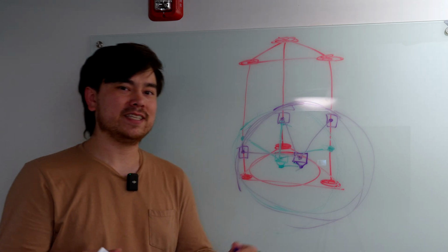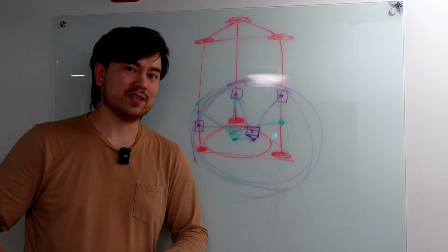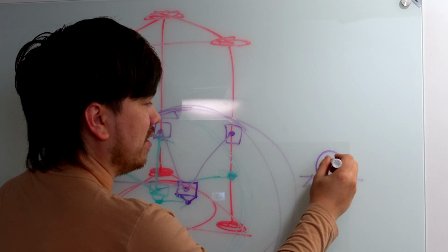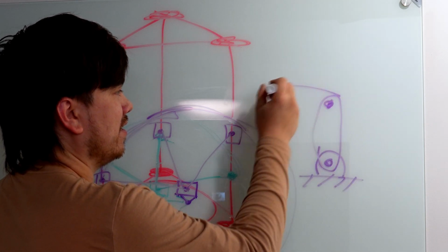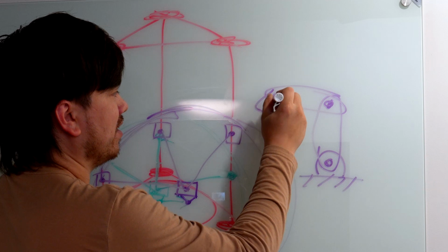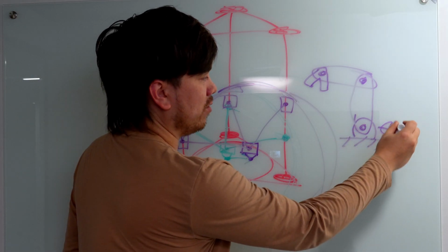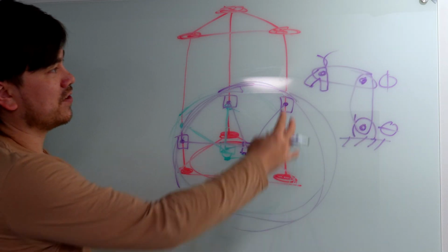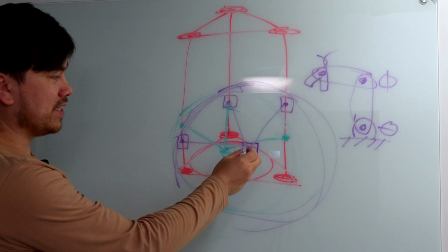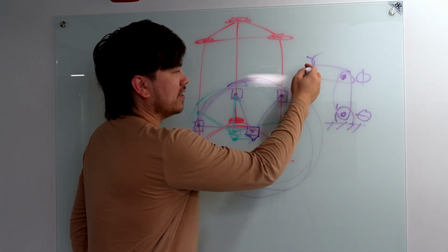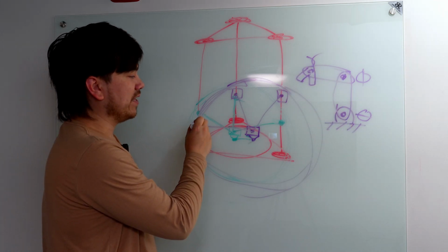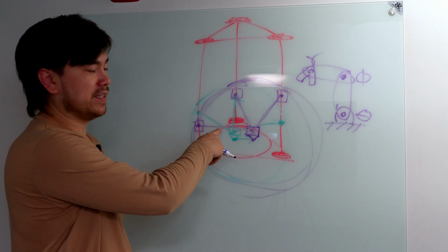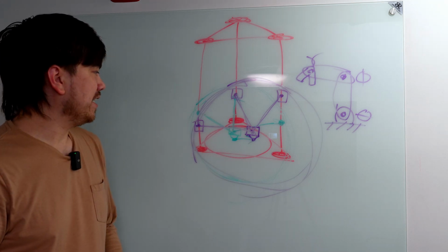They're not super complicated, but they're a type of mechanism called a parallel mechanism, which is opposed to a serial mechanism. Basically like a regular robot arm. You can think of this as ground. You got one link here, another link here, another link here, and then let's say you've just got like a gripper. This is a serial mechanism where you've got one angle, two angles, and then three angles. I don't know if you assign random Greek letters to them to describe where this end effector is going to be. Versus on this one, instead of these being one after another in serial, they're all in parallel. So they're all affecting the position of the end effector through some complex mathematical equation that's based on this sphere intersection problem.